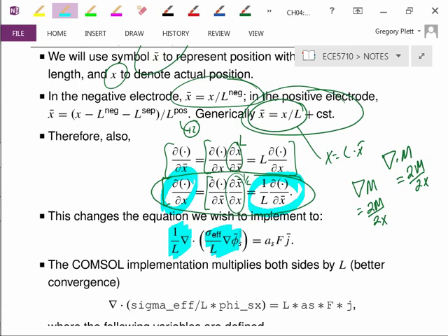And if the equations are not all scaled more or less the same, so that the right side and left side of the equation are more or less the same, then COMSOL ends up giving more emphasis to matching the big things than the small things.